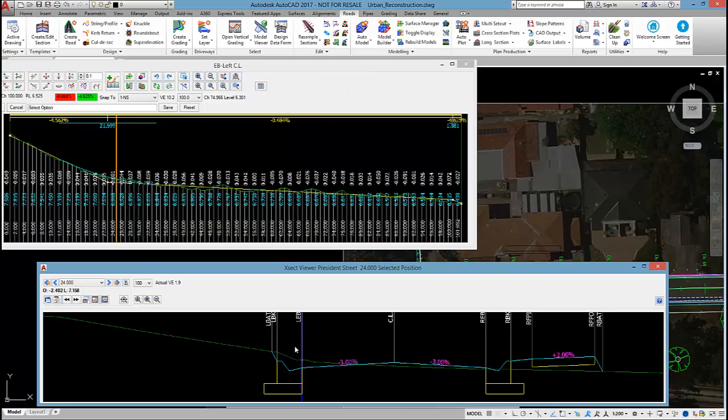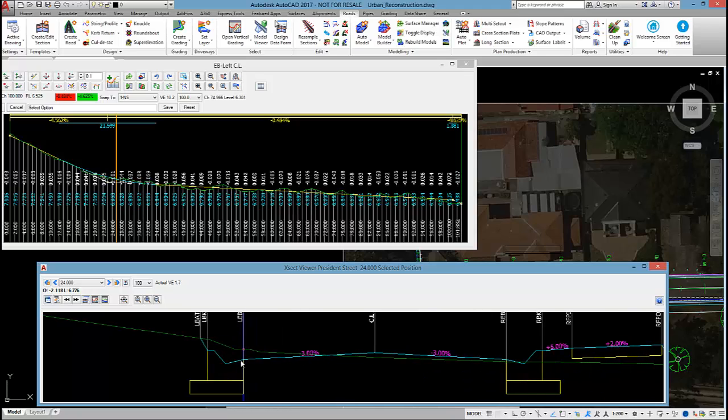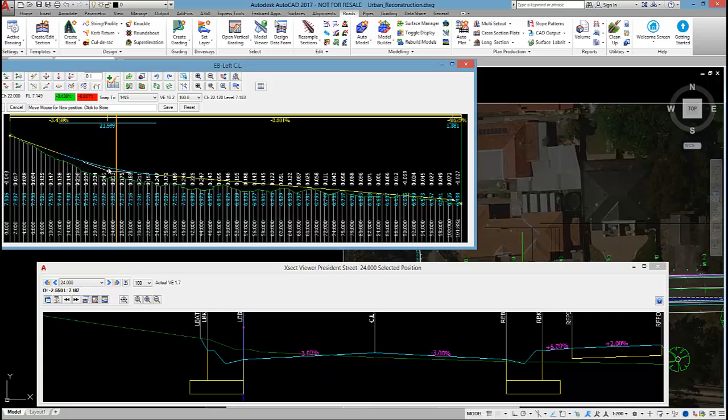So I use the road option to do that. And then when I click OK, you can see I've actually positioned the alignment where I created the template, so the curb is in the right position already. So I'm not too interested in the offset as such, but that pink dot represents the level at that location. And as I move the levels on the string, you can see that red dot updating.